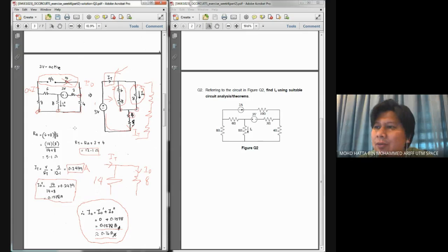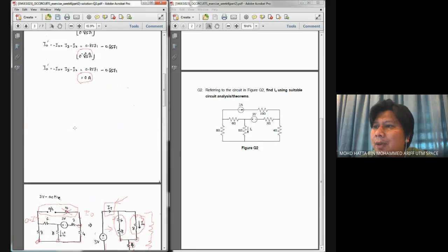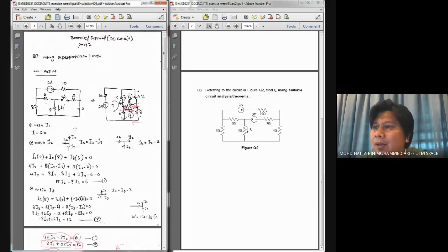The harder part is that if you've already done that one, and you try to simplify it, then this part, I think, is very crucial. The way you process what you have done for the superposition. You know that for voltage, you put it short circuit, for current open circuit, and then later on, how do you calculate this part?